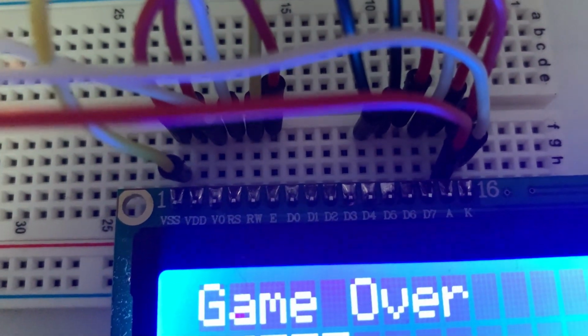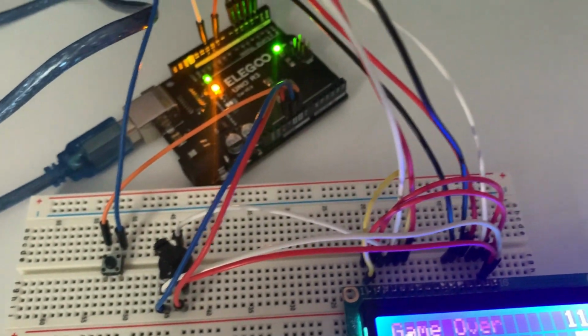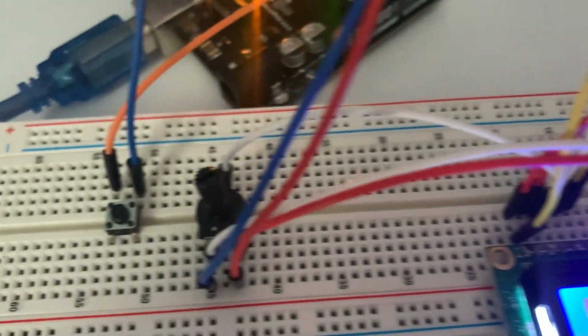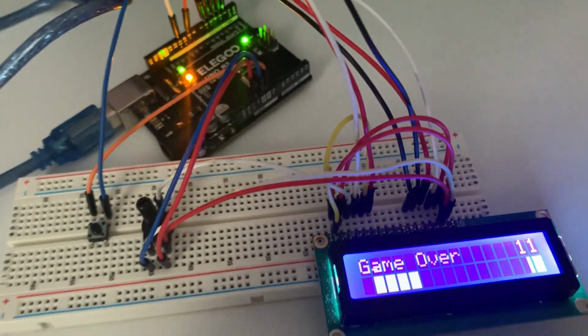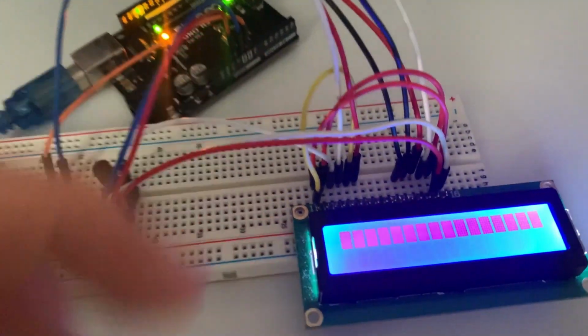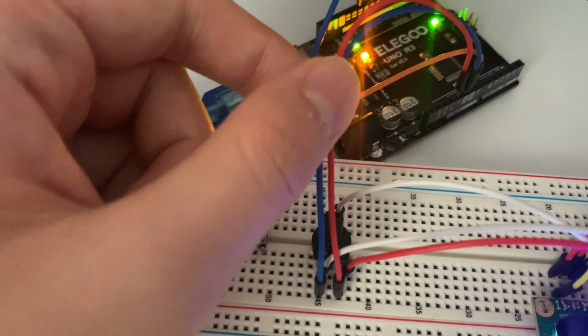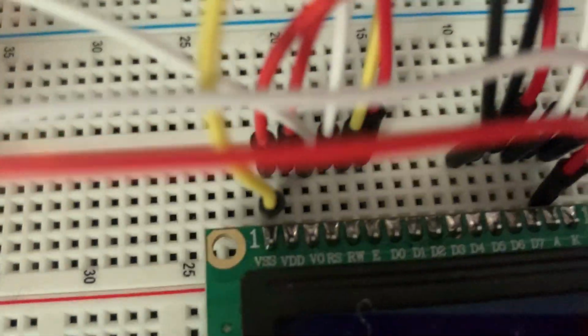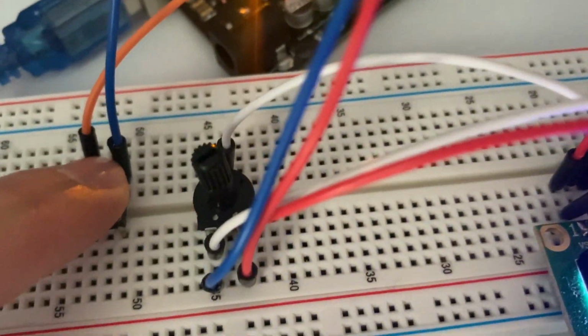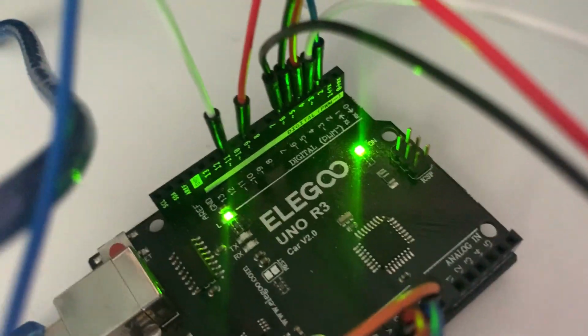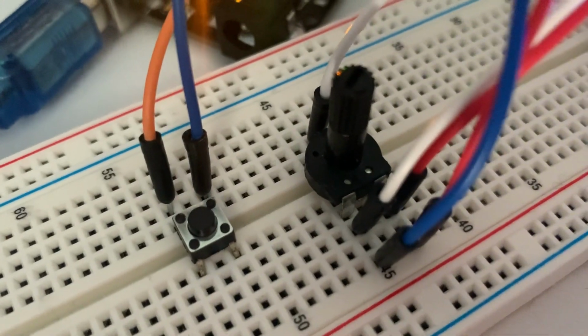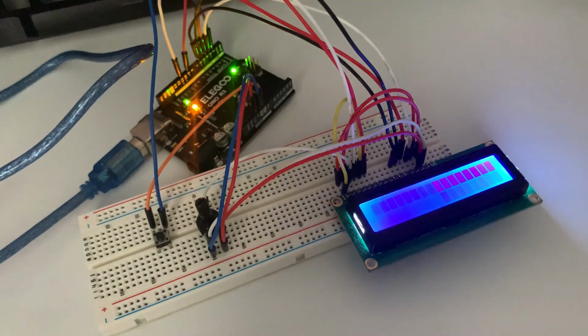This is my schematic on the breadboard. Let me try to get a good angle for you to see. You can see how all these wires, this first part shouldn't be too difficult because everything is seen on the schematic. But if you want to see this part, you can see how this one is connected to A. These are ground and 5 volt. And then this one is going a little bit crazy because some of the wires are not connected. I'll just reconnect it. VO. And then obviously you have the push button here, and those are connected to ground and pin number 2. Okay, so take a quick look at that. Here is what the potentiometer on my breadboard looks like, and here's one final look at everything.